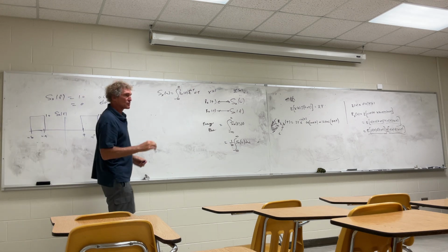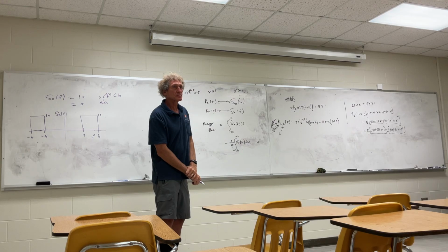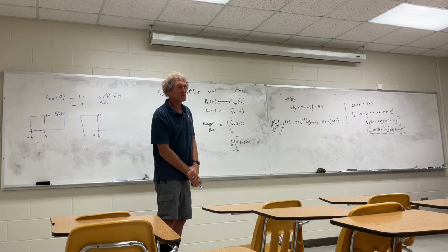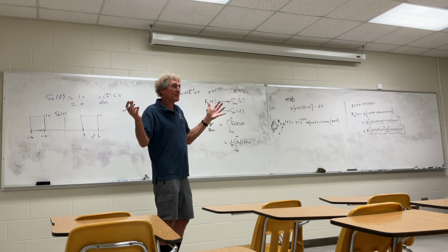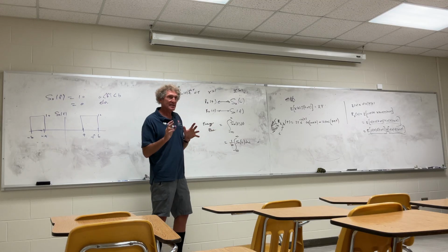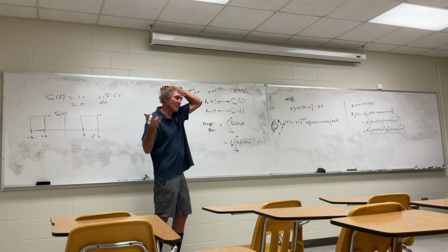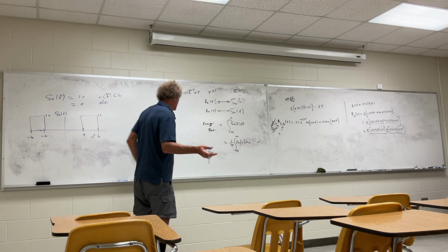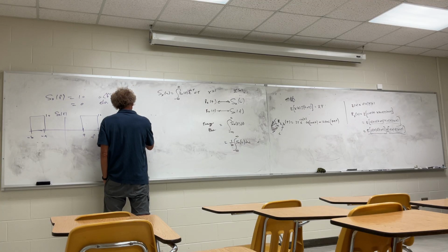What's his wording on this one? He asked to find the mean square value of the process if A equals 4 and B equals 5. All right, the mean squared value of the process would be the power, the total integral of S_x. Well, the process is typically a voltage for electrical engineering, so I'll call it the mean squared value.